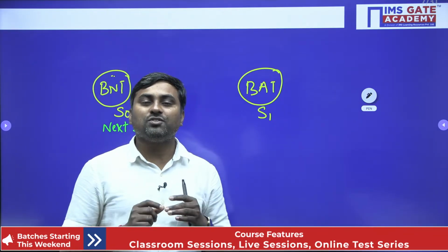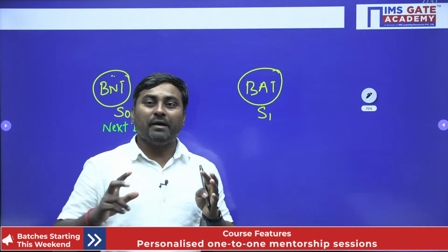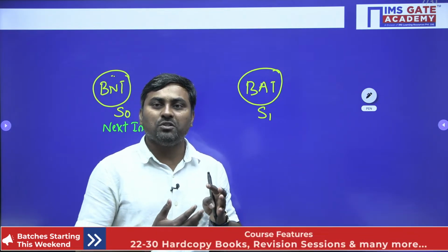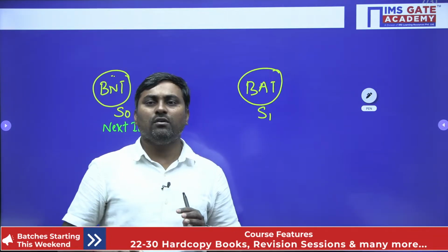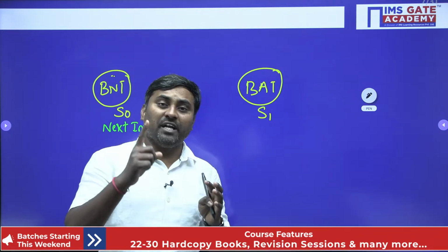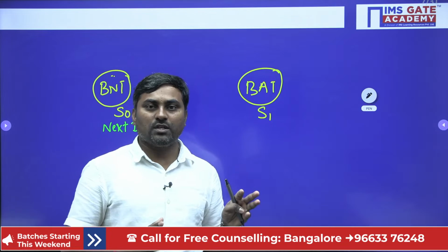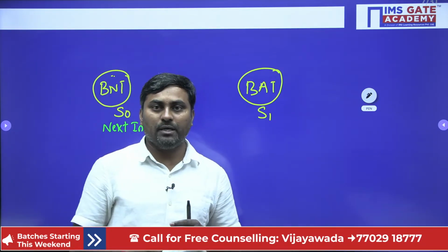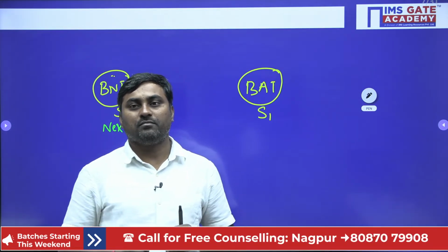Let's take an example: branch taken. Branch taken means my prediction is wrong. By that time, my sequential instruction got fetched, but it is jumping to the target instruction. That means you have to flush the full pipeline and then fetch the target instruction, because my prediction is wrong. When the prediction is wrong, the full penalty happens: the entire pipeline is flushed out and the target instruction is freshly fetched. This is case number 1.